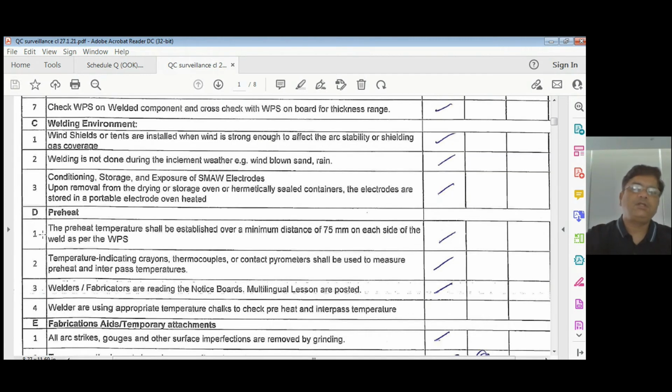So what usually happens is night shift is given the handover to day shift. Some welders are saying, okay, this I have not used much. This vacuum pack you can use in the day. And when we come to the day, it is saying that it is issued in night and already 10 hours have passed. So this electrode, either it should go for scrap, or it should be at least one time baked before you are going to be reusing that. Only one time it is allowed. So that is what it's all about, hydrogen pickup control.